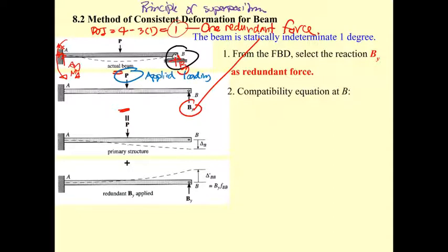The beam subjected to the applied force changes from statically indeterminate to statically determinate, a cantilever under the force P, and it is plus the beam subjected to the redundant force.